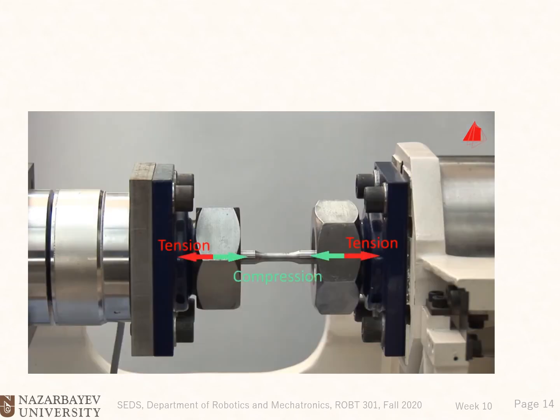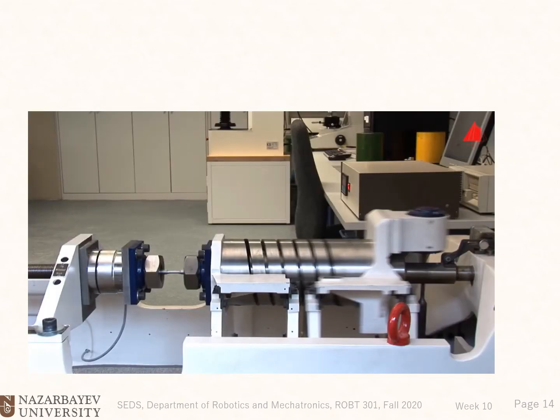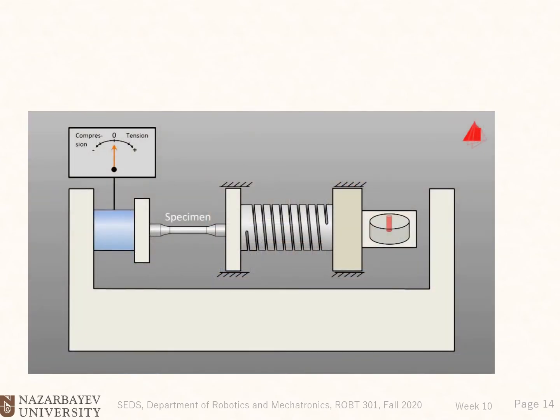Our fatigue testing machine is equipped with a mechanical resonance drive. The specimen is connected at its left grip via a load cell to the machine frame. At the right grip, a spring is mounted and there in turn a mass. An imbalance stimulates the mass to vibrate. Longitudinal guides prevent the mass from vibrating in the transverse direction. Via the spring, the test force acts on the specimen. By varying the excitation frequency of the imbalance, the test force can be controlled. In our case, the specimen is loaded with about 25 cycles per second.